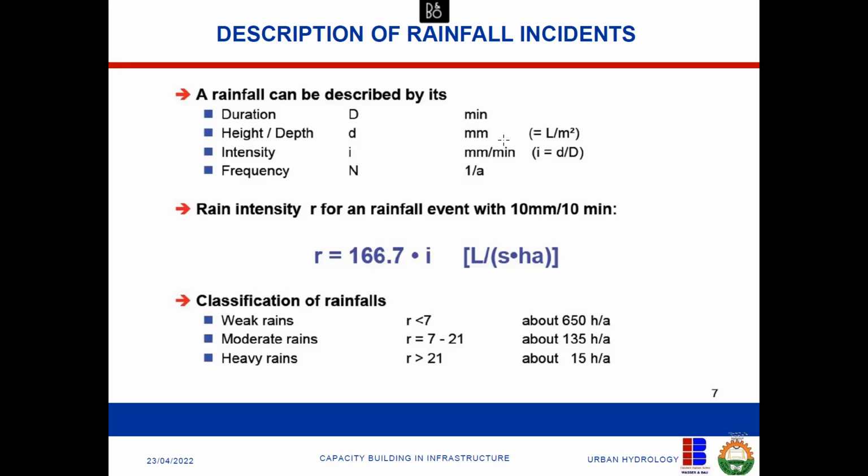So one thing about stormwater design is that the higher the return period, the higher the cost. That's why if you're designing for normal storm events, normal drainage, you don't use more than 5 years. You just use 1 or 2 years, meaning that the frequency is higher. But when we start using 1 over 25, that is about 0.4, sorry, 0.04. So you find out that that is now a lower frequency, and that will lead to a higher return period.